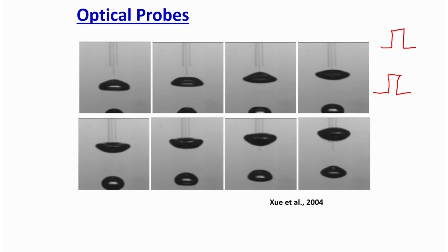But in reality, what happens is that the bubble is not just touching the probe in one go; it is staying some time with the probe. Because it stays some time with the probe, initially the value will be 0, then it will slowly start increasing, because now the bubble comes very close and is piercing. During the piercing, this voltage will remain the same, and then it will slowly decrease, and it should come to 0.